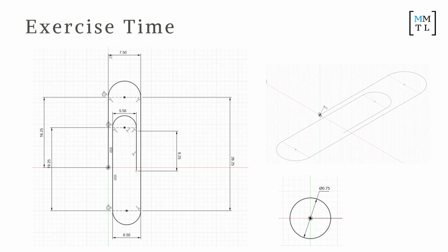And now around the origin, do a circle that's 0.75 in diameter. So don't worry, as soon as you click sketch, you'll get to choose a color. Or if you click finish sketch, you can always jump back to the sketch. And select the profile.